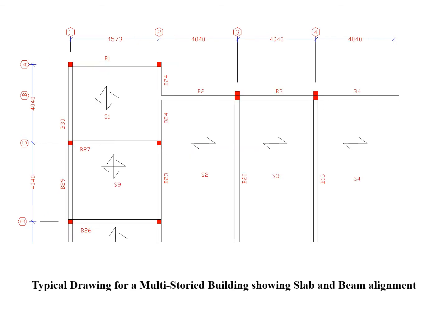Again, this is the spanning or the beam layout and slab layout for the systems. Normally, first at each corner of my building, I should locate the columns. Then the columns will be connected by means of beams. If the span of my beam is large, the span increases, depth increases. To reduce the depth of my beam, intermediate columns are inserted. Then the beams will be spanning between the columns.